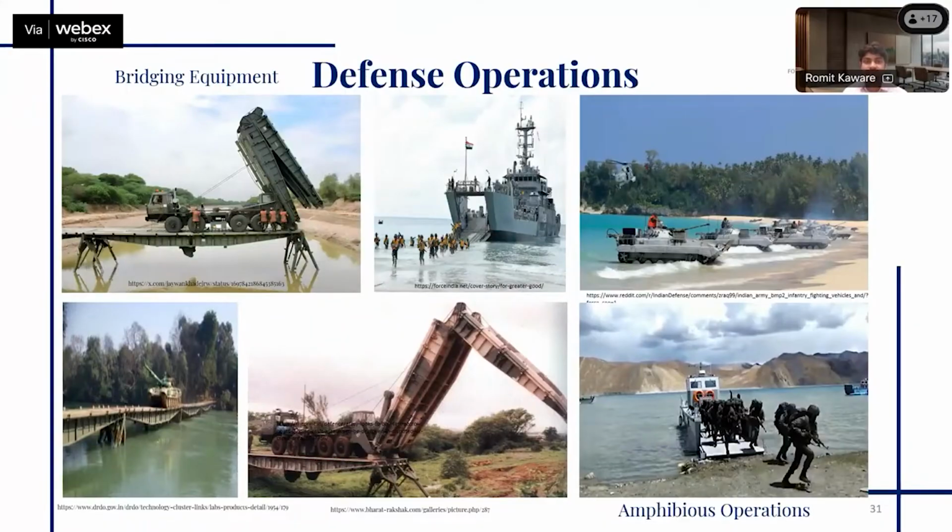This also finds its applications in mobile bridging equipment and in amphibious operations as well. So, in regions such as Sir Creek, if we need to deploy such bridging equipment, we really need to know what would be the maximum load that the soil can sustain without failure. Again, using remote sensing methods or acoustic methods, if we could have a large-scale mapping, a heat map of the sediment type and the sediment bearing capacity, it helps in proper tactical planning itself.